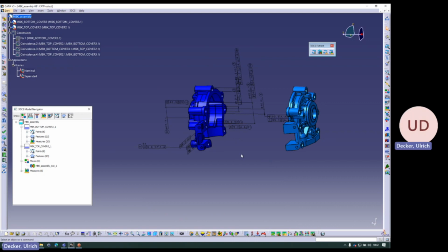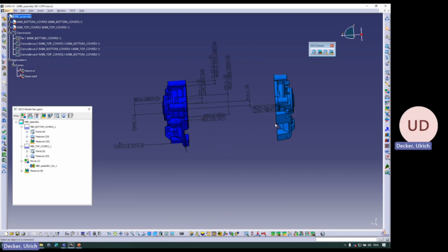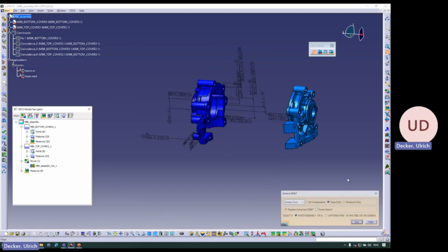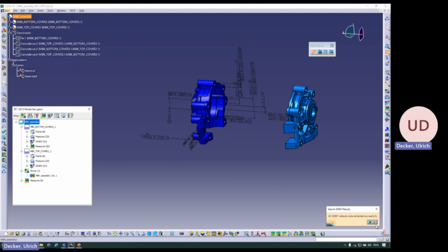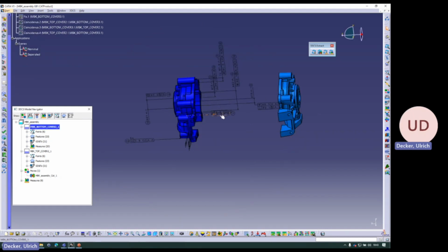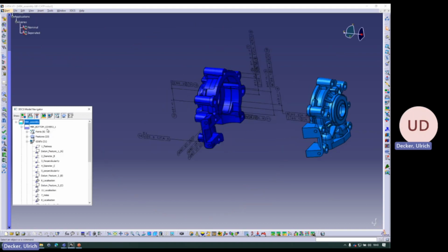The next thing I'd like to integrate is the 3D tolerances into the simulation. So I hit the next button and say, okay, let's import those 3D tolerance information. Of course, out of those 3D tolerance information, you can also hand it over to a drawing, and this is an internal loop. When we update tolerances here and you open the drawing and hit update, they will be updated as well. However, now we also have integrated the tolerances into our system, as you can see here.